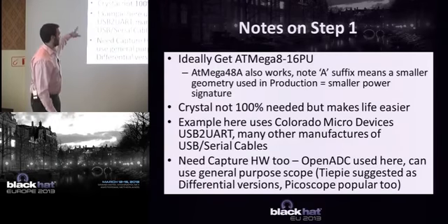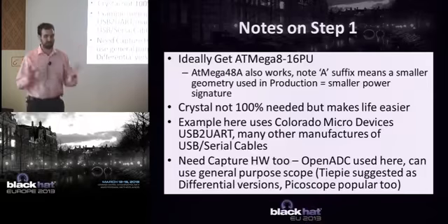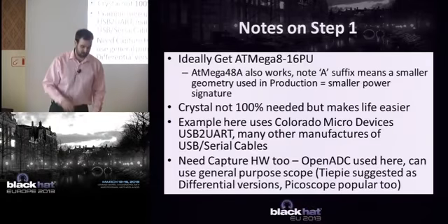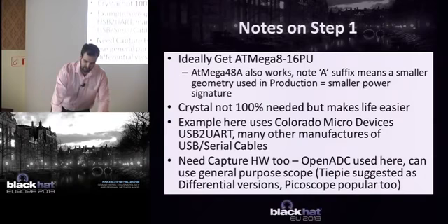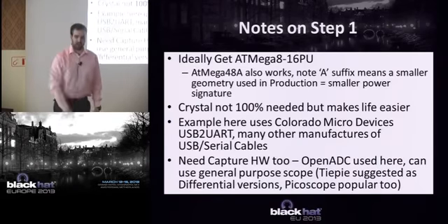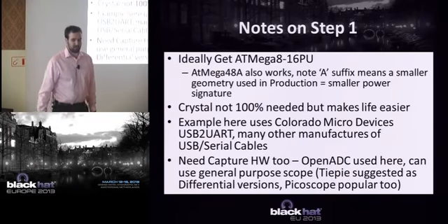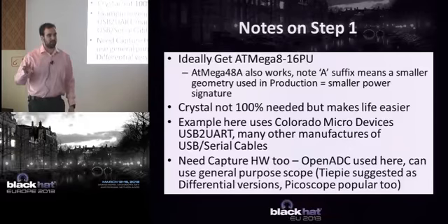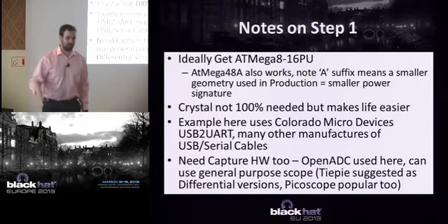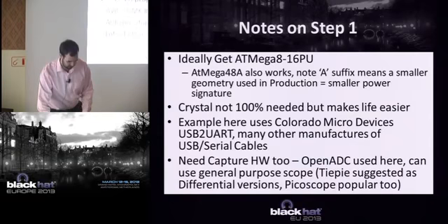And I happen to use a specific USB to UART, but there are tons of manufacturers, SparkFun or whoever else makes these types of things. You do need the capture hardware. Here I'm showing this OpenADC board I've designed, but you can get away with general purpose scopes. If you're attacking this very simple board, you can probably get away with something like a 100 megasample type scope or similar.